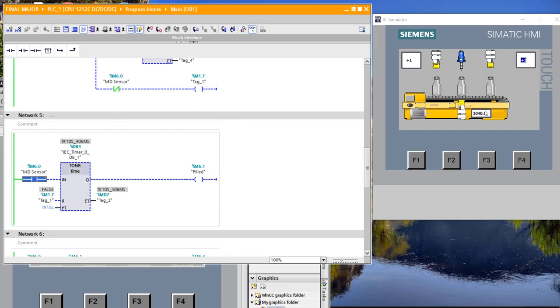So in this case our solenoid valve has been stopped and the sensor has failed, so it will not indicate anything. And ignore this, the motor has been started. Now the motor is starting. This is a bug, which we have to repair. So our task now is to stop our motor at this point, so that we fulfill our needs and our system is working properly.